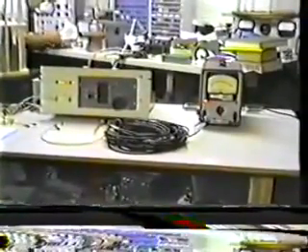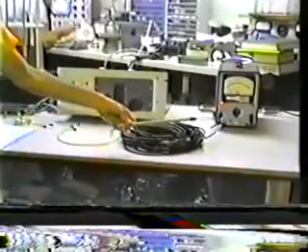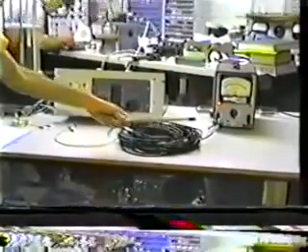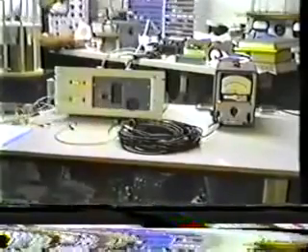Now what's going to happen here is a series of impulses, alternating electric impulses, will be produced by the radio frequency oscillator and launched down the cable with a finite propagation velocity. These impulses will travel around in the cable, reach the open circuit at the end of the cable, turn upside down, and reflect back, and again be delayed and return to the oscillator.